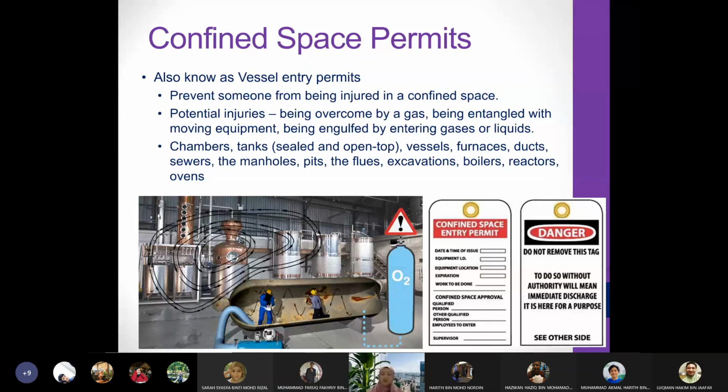That's why when you are in a confined space, you have to have this permit, and you have to put up these warning signs to say that there's somebody in there. Don't put any kinds of gases or liquid in there. You don't want to drown that person, or create any fire or sparks around it, because there's somebody in there. Okay?